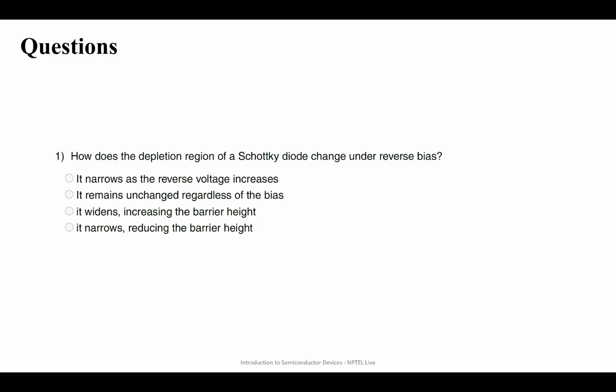There the heterojunctions are basically different types of semiconductors. So you have a large bandgap semiconductor, then you have a small bandgap semiconductor, then again a large bandgap semiconductor, and the small bandgap semiconductor is very thin. It's like 1 to 2 nanometers or even thinner than that. So what happens is the electrons and holes, the carriers, cannot move away because of the barrier